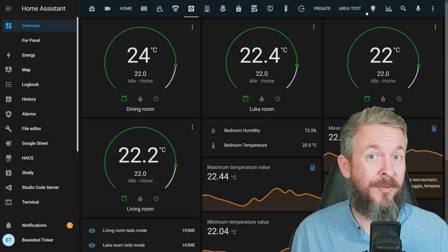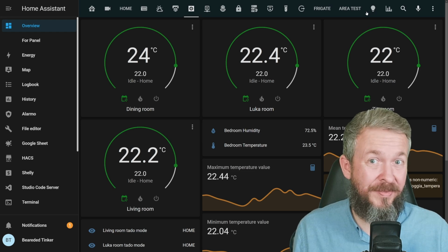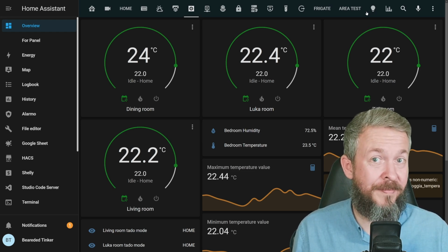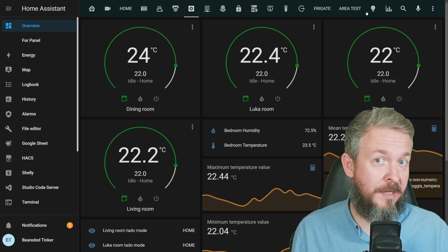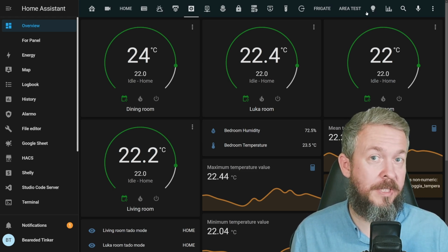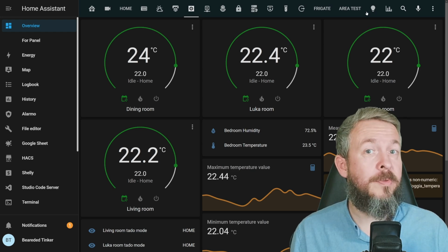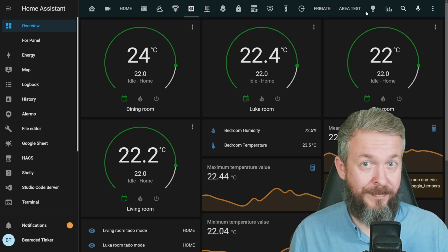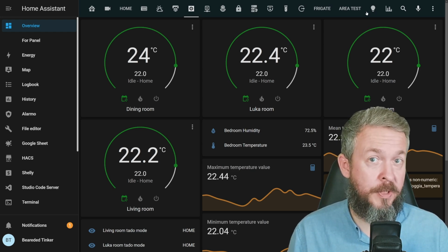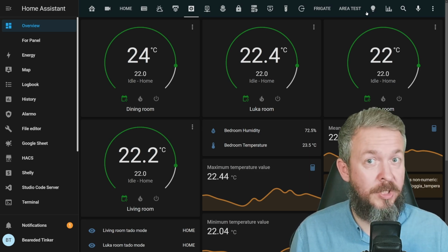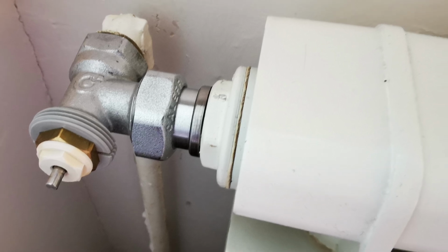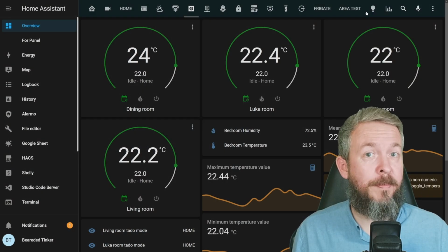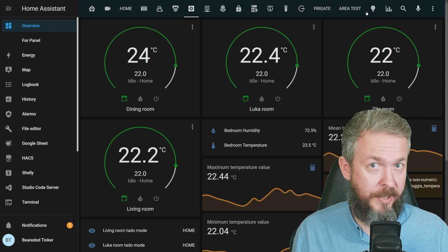For example, if you leave the apartment, the apartment would still be heating. But you can reduce the heat used, if the utility company is measuring this utility that is consumed, by using the smart thermostatic valves. There are tons of options for valves, but for this you also have to have radiators that are compatible with them. If not, you will have to call your plumber and replace the valve on the specific radiator.